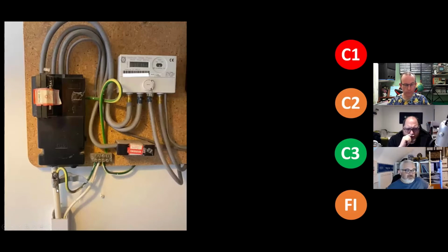That definitely looks like a PME cable. It's so thin and skinny. Yeah, I mean, been painted. Why did they put that earth on there then? That to me looks like a late 70s PME install where someone has gone, oh, that can't be right. Stripped it back, clamped onto the armour or the concentric, gone, there you go, job's a good one, not realizing. And they probably thought it was a TT and they'd convert it to a TN-S. Who knows? But there's a story of many, many weird things going on there.